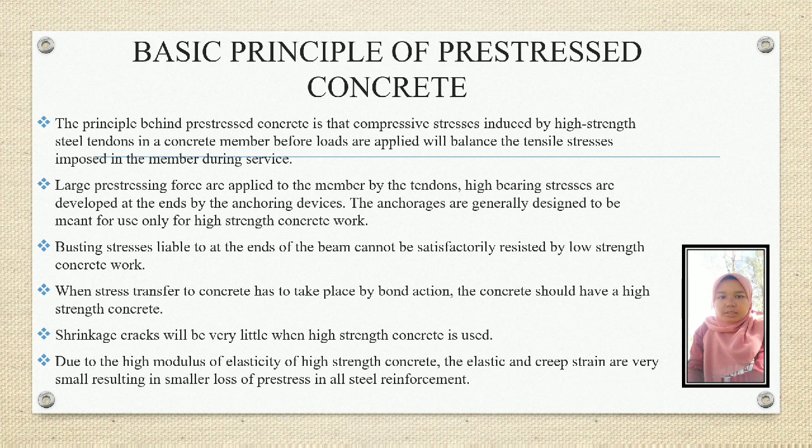Second, large prestressing forces are applied to the member by the tendons. High bearing stresses are developed at the ends by the anchoring device. The anchorages are generally designed for use only with high-strength concrete. Bursting stress at the ends of the beam cannot be satisfactorily resisted by low-strength concrete.